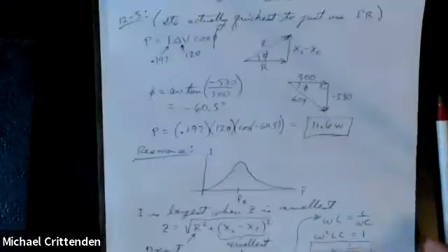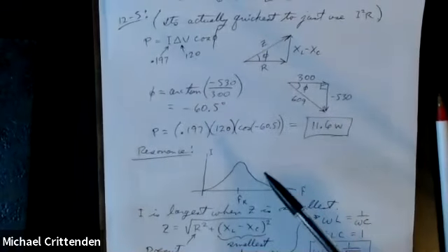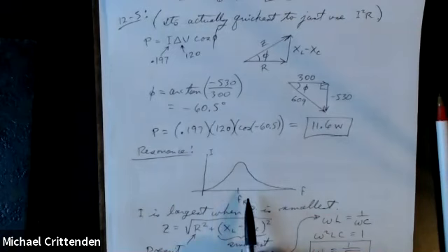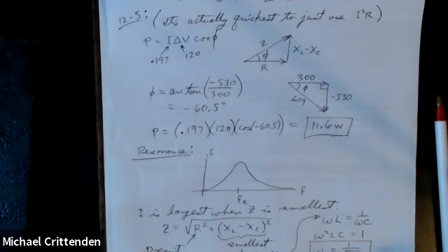After the signal has been induced on your antenna, you use a circuit similar to the one that I was just talking about here, and adjust its resonant frequency to the frequency of the radio station that you want to listen to. There are ways of making adjustable capacitors, variable capacitors.